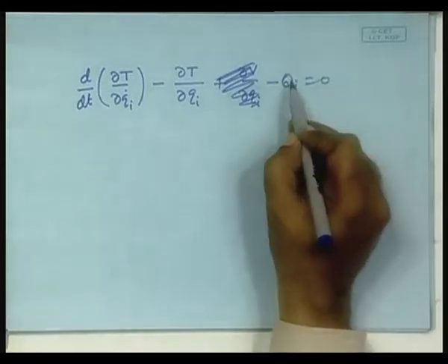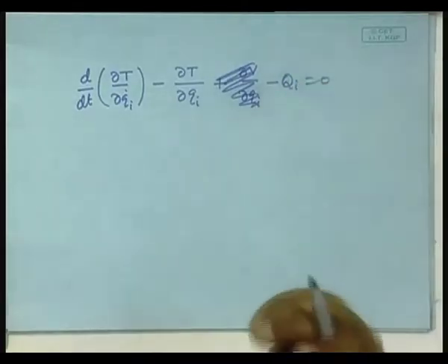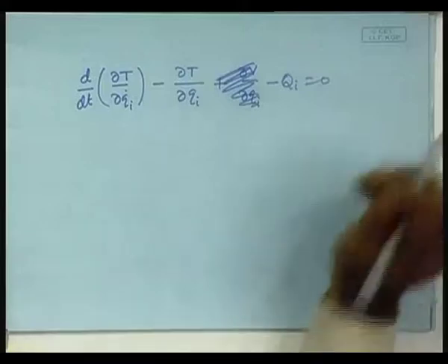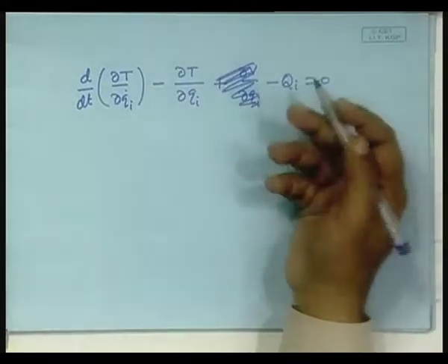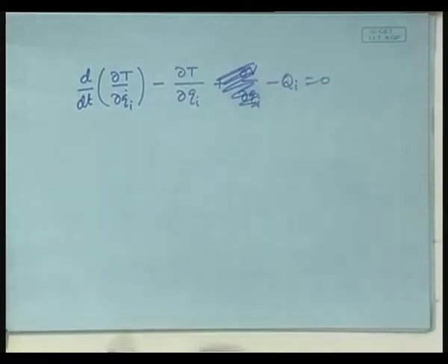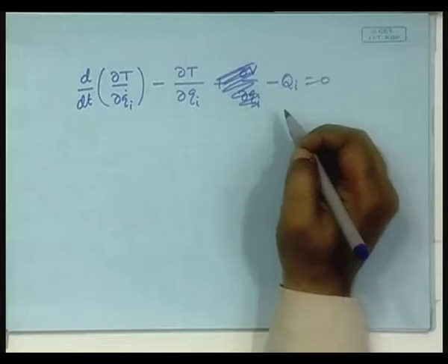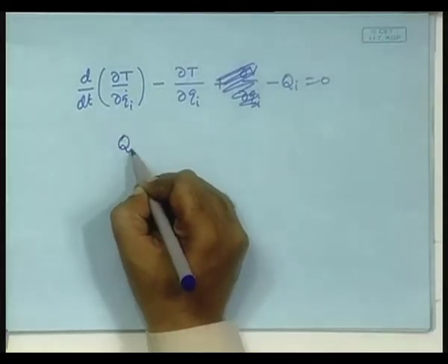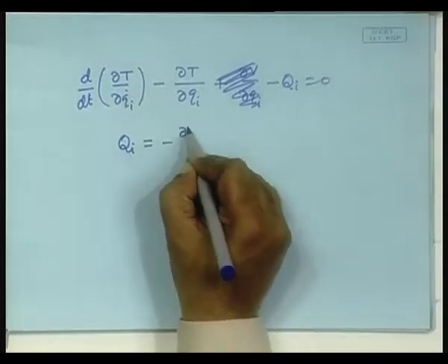So, this is where the generalized force term appears, and so long as there is no dissipative term, no friction term, no resistive element in the electrical circuit, this term can be obtained by differentiating the potential function V. That is how we proceeded. But now we find that in the new framework where we need to include the resistive things, Q_i earlier was expressed as this only.